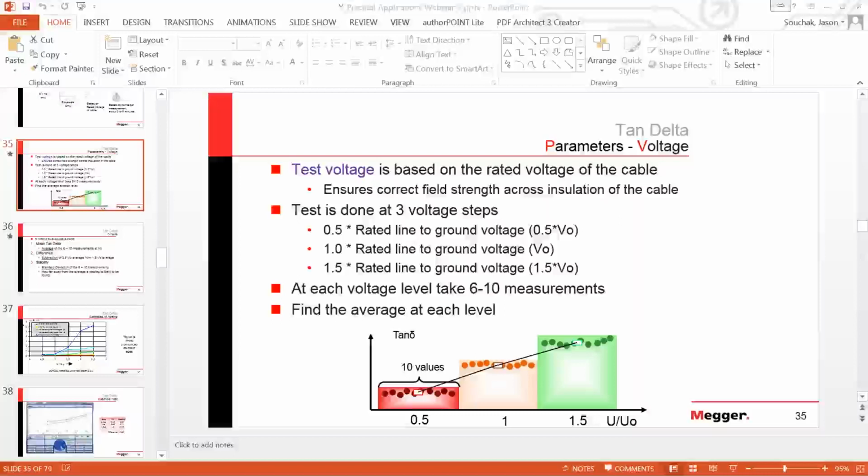Okay, it's basically coming down to the temperature or loading. Typically, loading equates to temperature because I have more load on it, I have more resistance, so I get a higher temperature. And the aging of cables, these aging processes that we have in the cable, are basically chemical reactions that change the polymeric material, or that change the paper when I have paper cables, oil insulated cables.